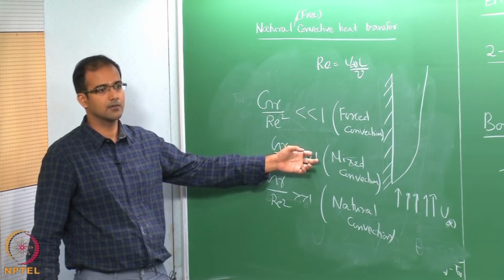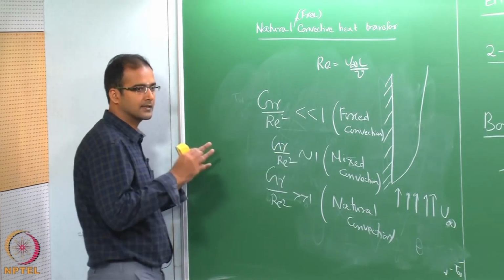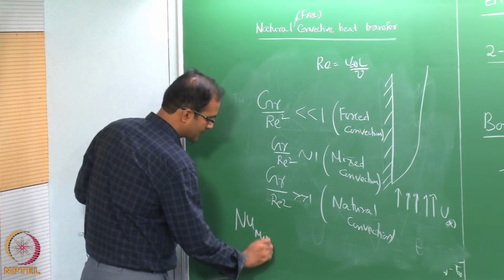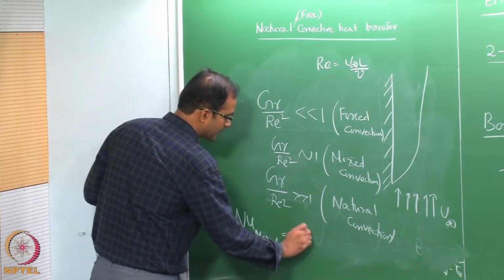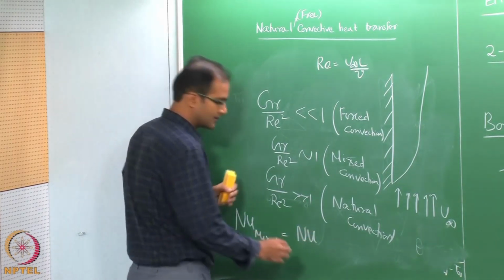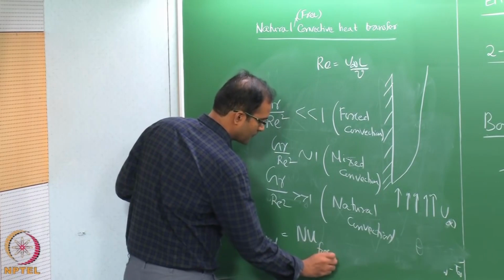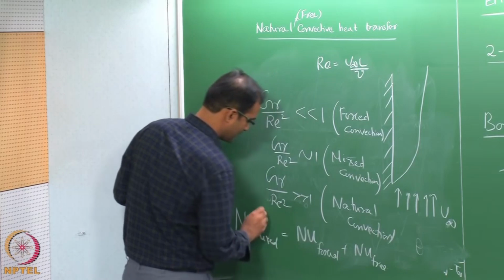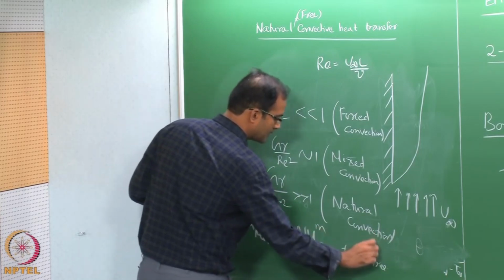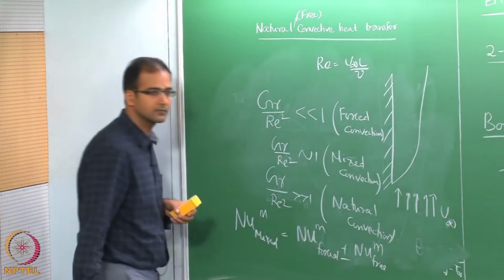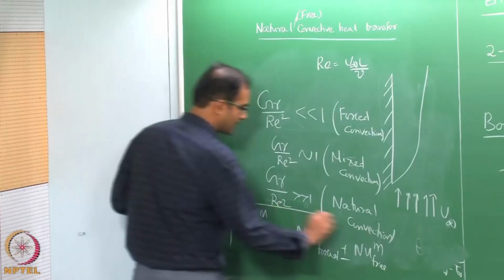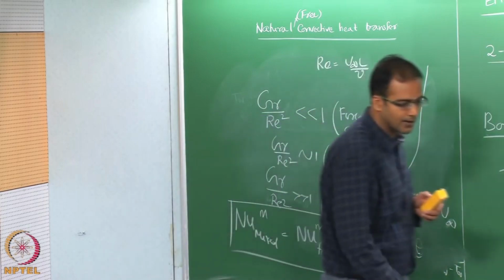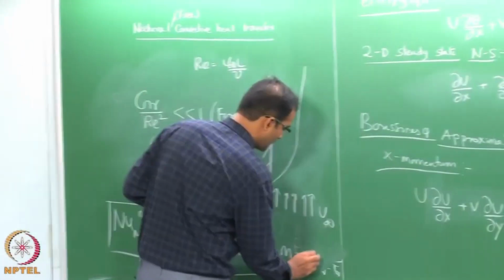Okay. So, in mixed convection the simplest way of approaching this is that the Nusselt number is simply calculated from independent correlations for forced convection and free convection, and we just use some power law to blend these two. Okay. So, this is one of the simplest approaches. Here the value of m could be either 0.3 or 0.4.